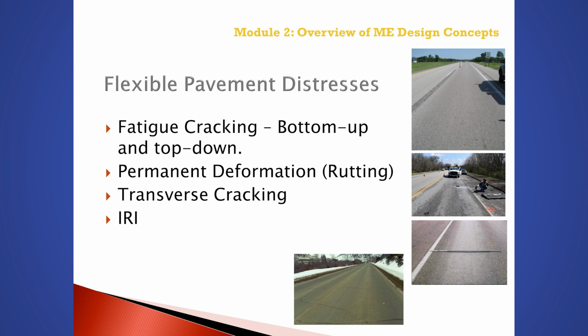Alligator fatigue cracks are a series of interconnected cracks that form an alligator cracking pattern. These cracks start as short, longitudinal, and/or transverse cracks, and with continued wheel loadings, interconnect to form the alligator cracking pattern. These cracks are measured on an area basis and converted to a total percent of the lane area, and the total area does include the wheel path and non-wheel path areas.